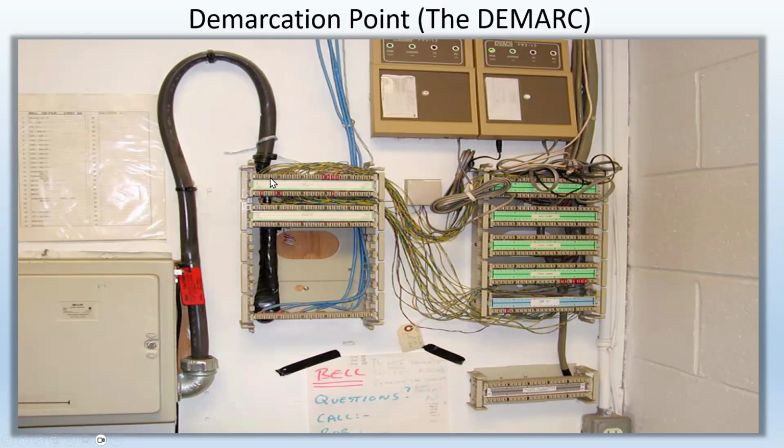Now, after you terminate that, you flip it around so the terminated wire is at the back of the connector, and you can use the cross-connect wires to grab the connection from the front and cross-connect that anywhere that things need to be connected. So this would be a field wiring here, for example. And those wires can be going to a shoe store in the mall, to a barber shop in the mall, and whatnot. So you'll have telephone lines coming in.